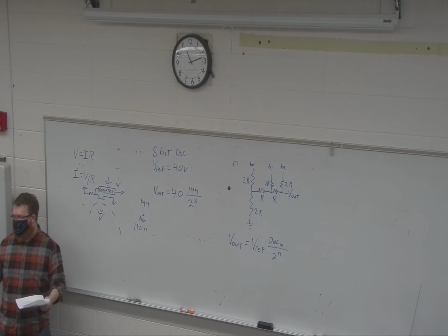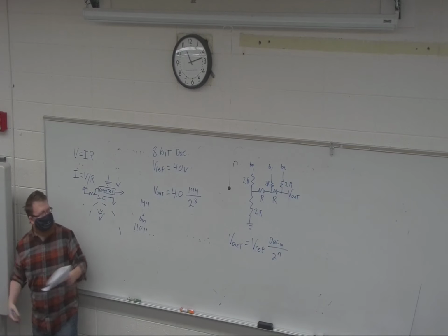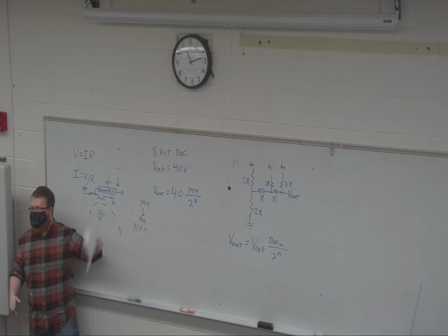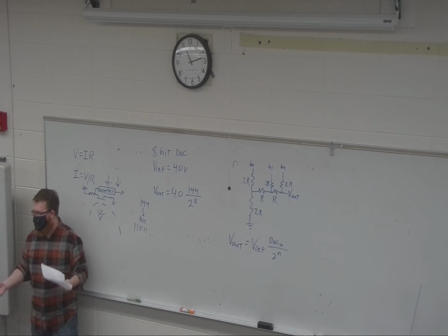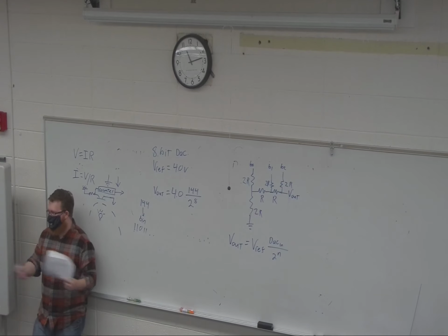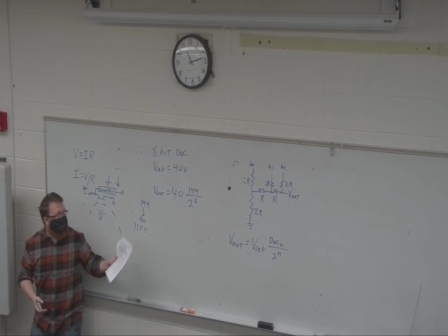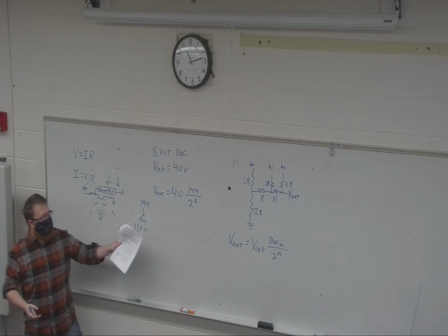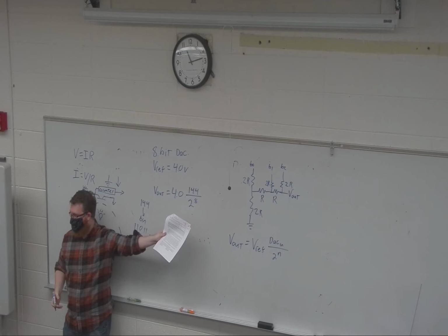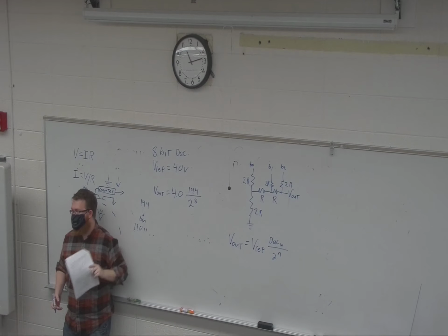But it is entirely possible in modern logic systems to program in decimal. The synthesizer, which is like a compiler for code, will take the decimal and turn it into binary. So in this case, 144 is sufficient because we know it's the 144th code, remembering that it is 0 indexed. You start counting at 0.